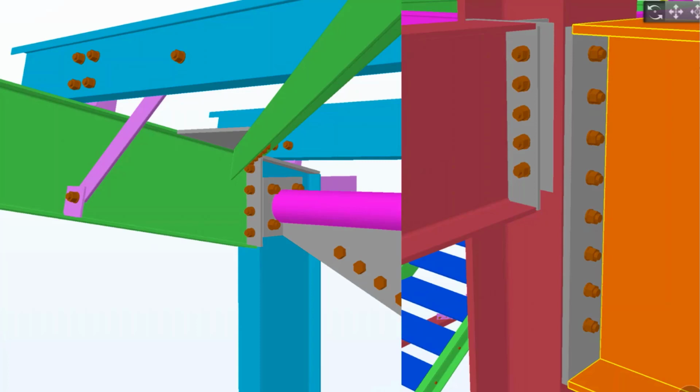Here are some other examples. For instance, there's once again another pipe bolted onto a column, an end plate on a beam, a little knee brace stabilizing a rafter, and then a purlin connected to a beam there, and then some bracing coming into the corner here. Then there are some deeper and quite large connections on the right-hand side. So these are quite heavy beams, and the right-hand one's a plate girder bolted onto a column. So this is all from a Tekla model.